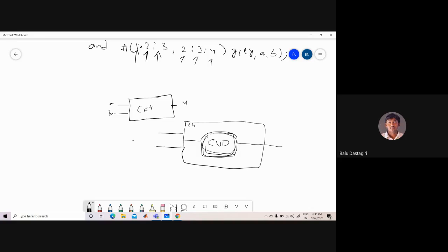Okay. So therefore, the test bench here is the top level module. Whenever we are writing the test bench for a given program, the test bench becomes the top level module. So this we have to remember. Whenever we simulate a program, the test bench becomes the top level module, and the circuit under design or circuit under test will be the sub module of that.